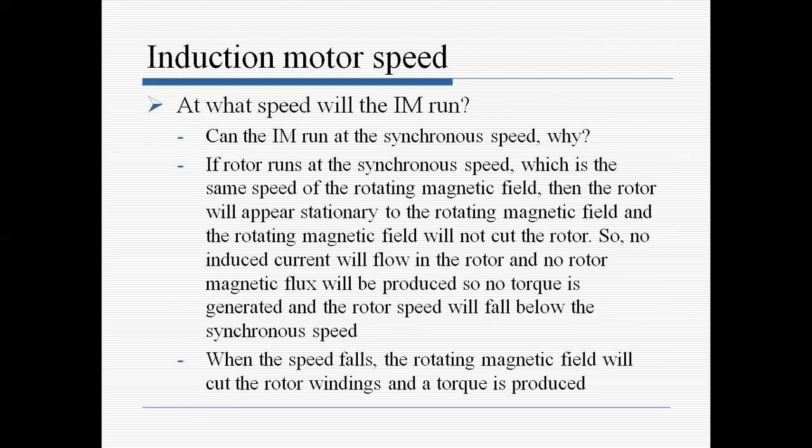Now the next question arises: can the induction motor run at the synchronous speed? Our stator flux is rotating in the clockwise direction at the synchronous speed. The speed was already found: N equals 120 f by P. Now the question is, can the induction motor run at the synchronous speed? The answer is no. Now why?